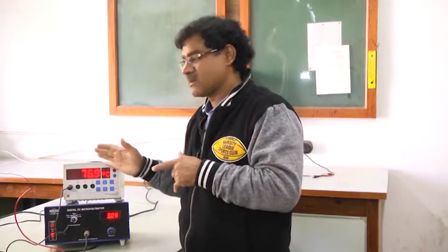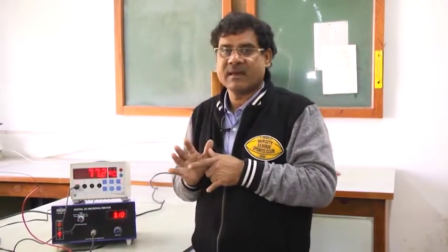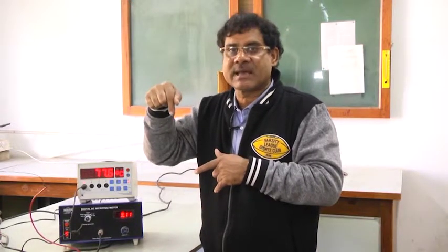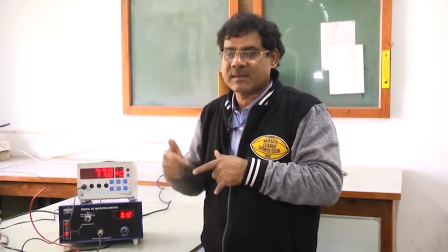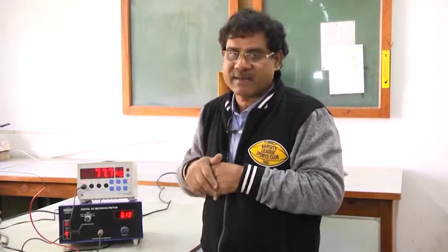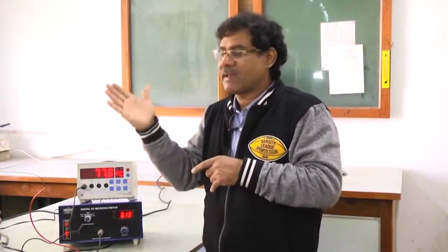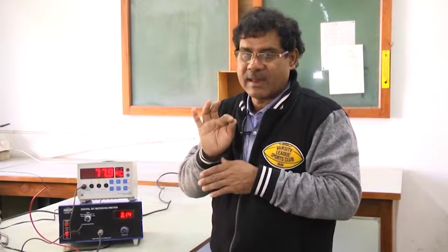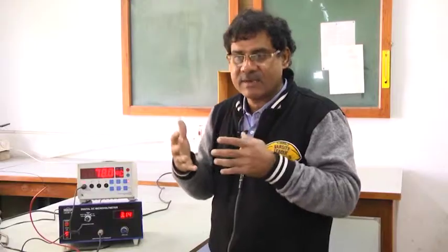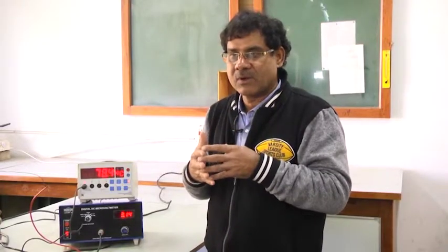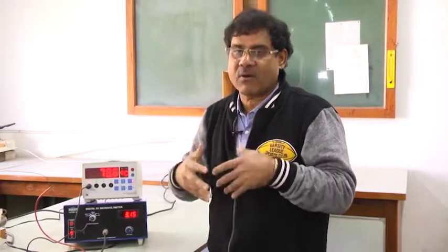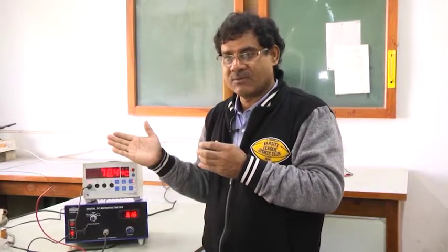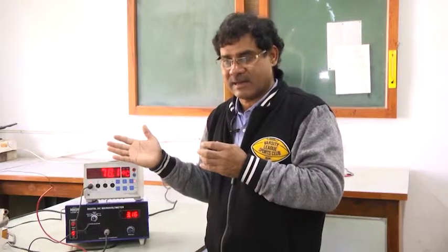Okay. So this thermocouple is very useful, because when you use a mercury thermometer, you are just observing the reading, right? You are not converting to an electrical signal. Okay. So these are non-electrical, and for interfacing you need to convert temperature or pressure or force into an electrical signal.